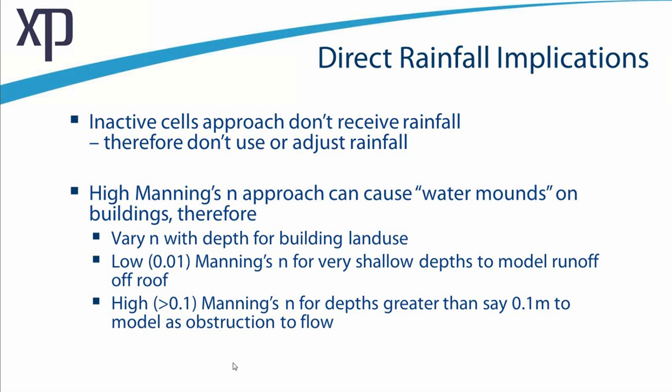If you are using the high Manning's N approach on buildings, you have to be a bit careful, particularly where the buildings are outside the floodplain, as the direct rainfall can tend to mound or build up on top of those buildings because it finds it hard to escape off the building surface.